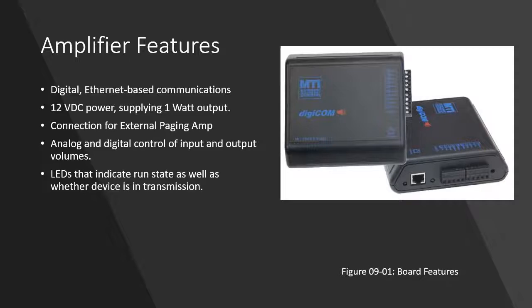The device uses 12-volt DC power and supplies 1 watt output for the speakers that it connects to. It has connections for external paging amp, which allows you to go up to 60 watts of output, and it provides analog and digital control for input and output volumes. It also provides LEDs to indicate run state and also whether the device is in transmission or in page.